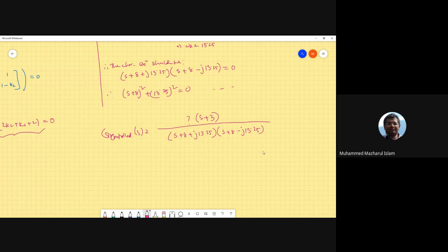Now you can say, why don't we use an extra pole here, s plus 3? Ultimately it reduces to second order, but if you need another pole, how will you manage the gain? You have only 2 gains, so you cannot expect to position 3 poles at our desired locations by adjusting 2 parameters. And that was the original reason why we opted for state space controller design, because we didn't have enough parameters in PID controller design.